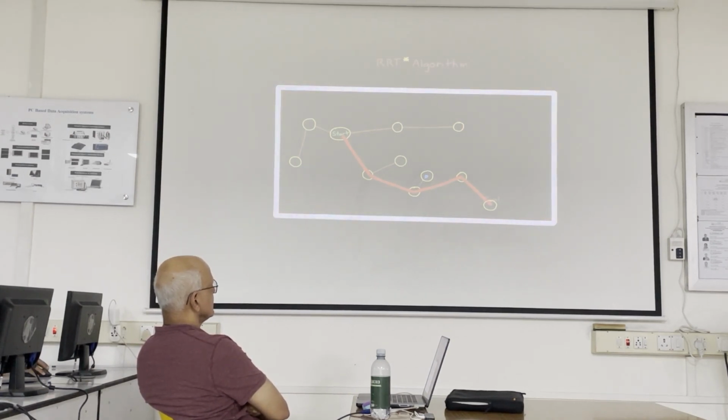The difference, however, comes from where we connect this node to the existing tree. We don't necessarily connect it to the nearest node. Instead, we check for other nodes within some specified search radius and determine if we can reconnect these local nodes in a way that maintains the tree structure, but also minimizes the total path length. So here, I'm connecting it to this other node, since that's going to produce a shorter path back to the start.